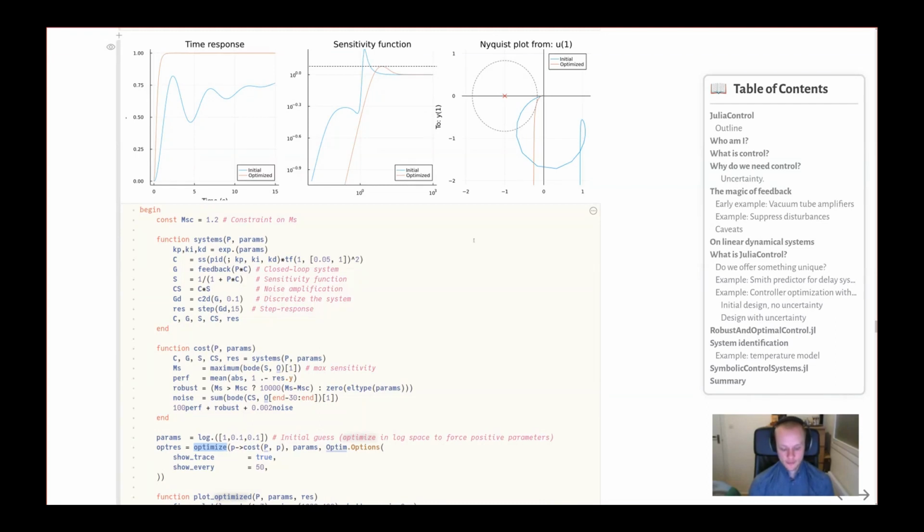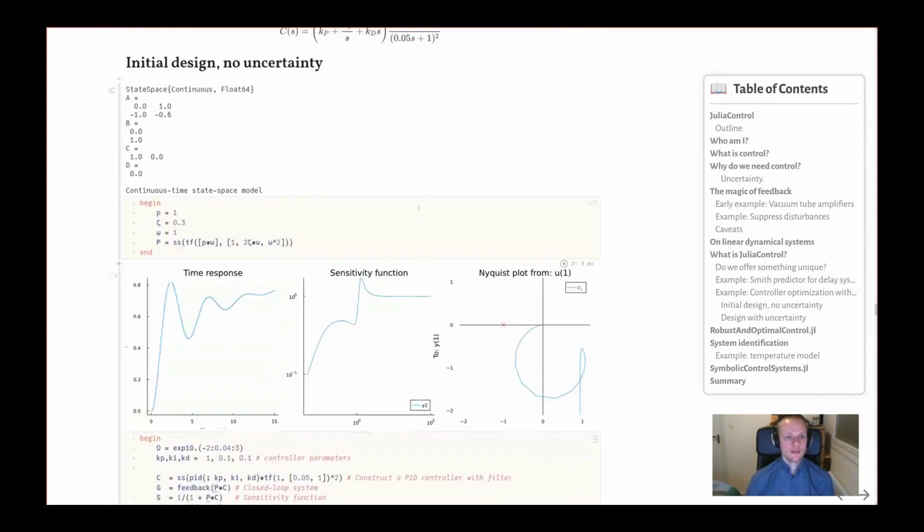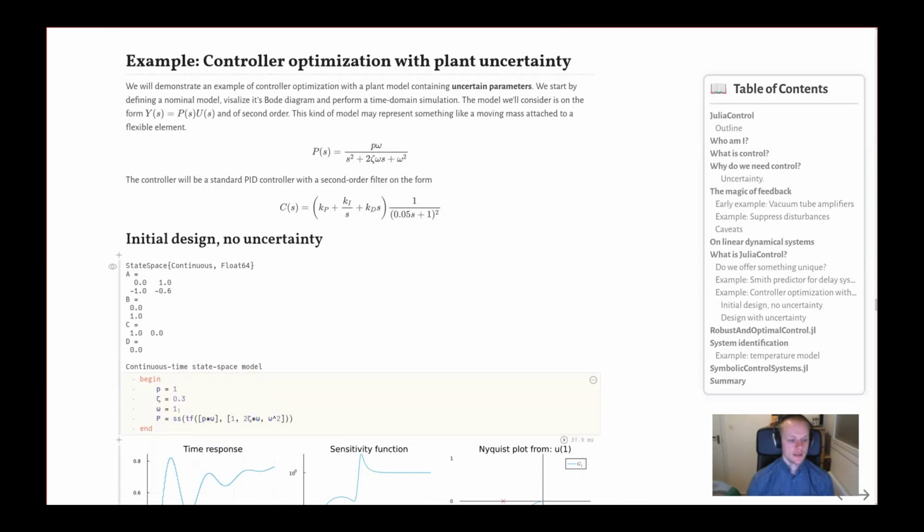Yeah. Thanks for those questions. So here I make use of a model of the system, as you point out. So this is my model of the system here. I have chosen the parameters. So there are multiple ways of obtaining such a model. Either you go and physically measure things such as masses, lengths, and you write down the physical laws of motion or whatever physical insight you have and derive the differential equations. And that is one way of obtaining a model. So that we typically call it a white box model because you know everything about it.